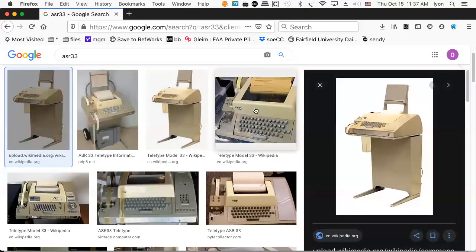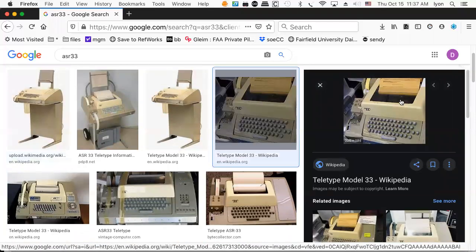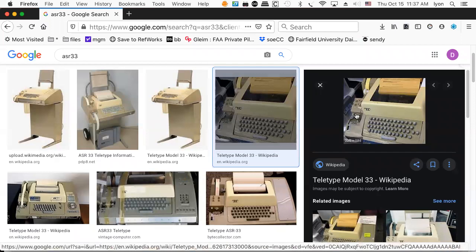This is an electromechanical device, and I don't know if you can see it, but in here there's a little area called the platen, and then there's this carriage. The carriage has a little type ball on it, and what it does is it advances the platen to get to the next line, and then the carriage goes all the way to the beginning. So advancing the platen, that's a line feed. Getting the carriage to go all the way to the beginning, that's a carriage return. So you do line feed first and then carriage return. Actually, you do carriage return and then line feed, because carriage return takes longer.